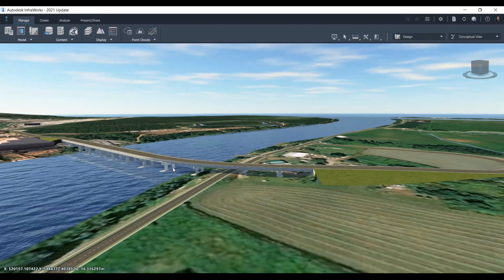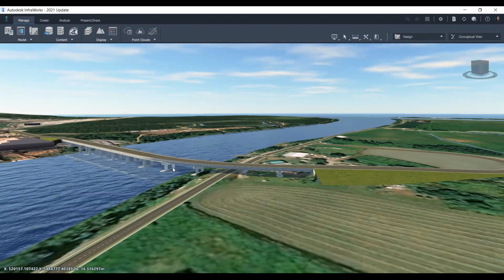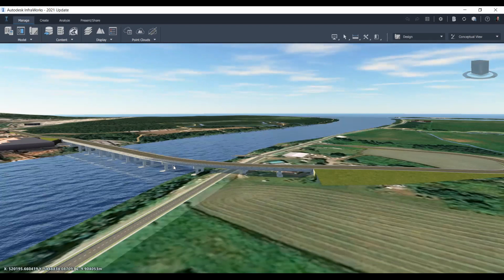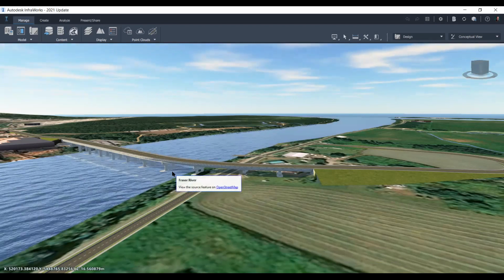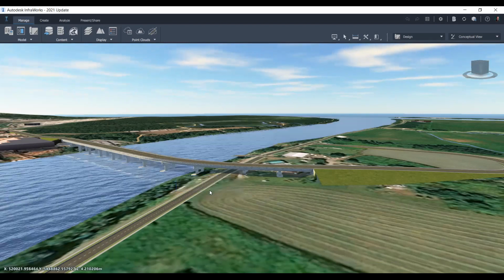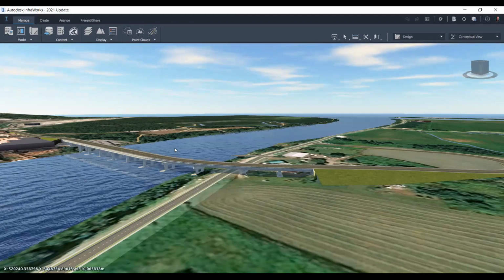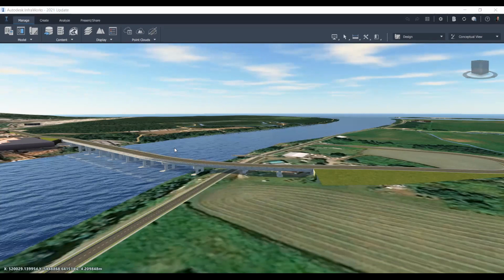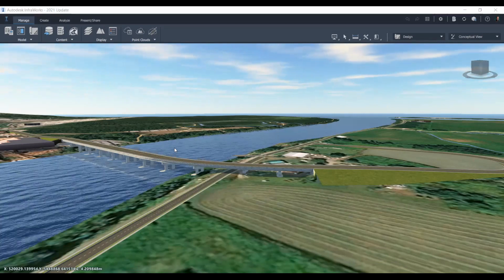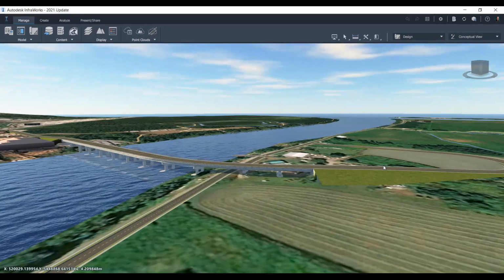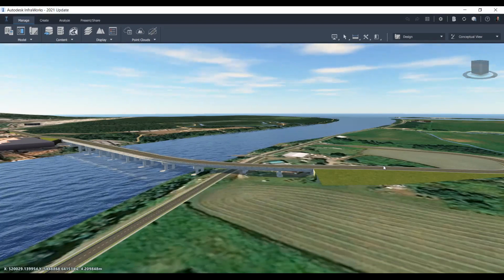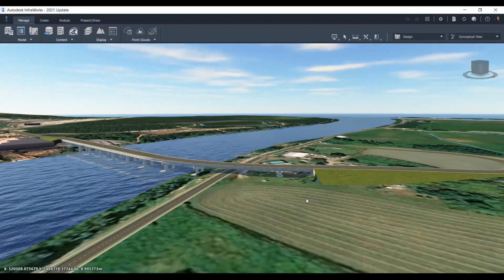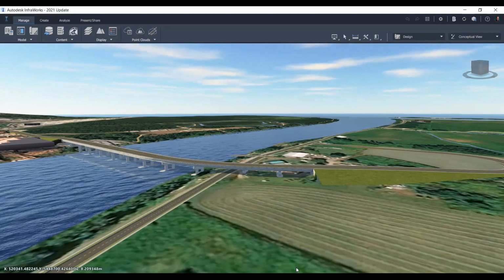Because it came in as a component road, I can just add the bridge. Now, if I go back into Civil 3D and make a change, come back here in InfraWorks and essentially reload it, sort of like an XREF, but different, of course, this bridge will update itself. So if the road ends up going higher, the bridge, piers, and everything else will update. So it's a dynamic relationship between your Civil 3D corridor and the InfraWorks component road, which is very nice.